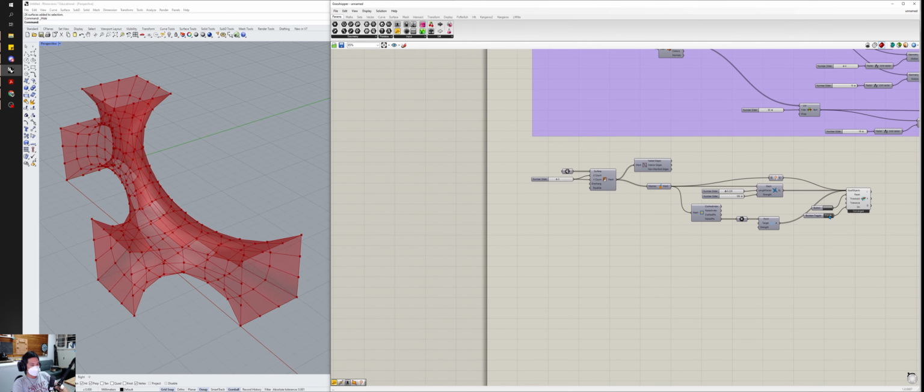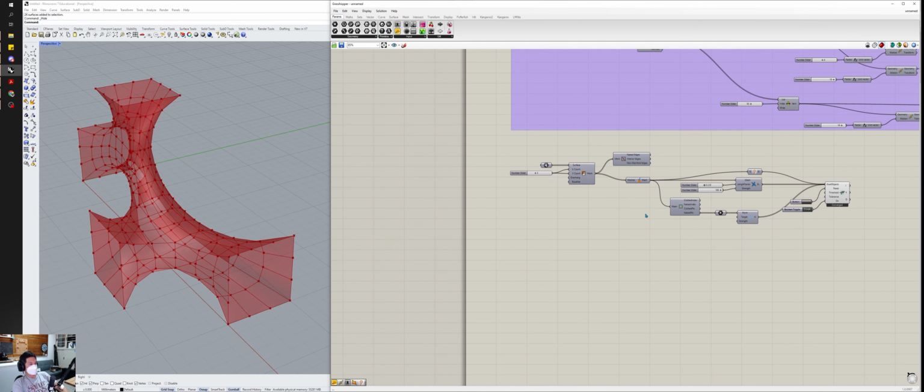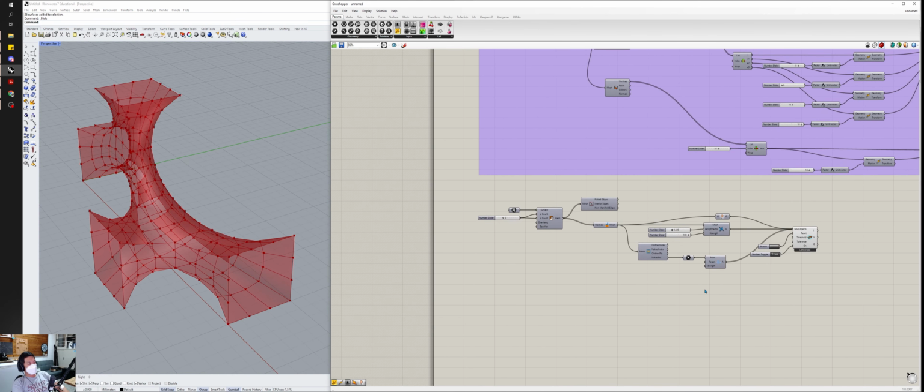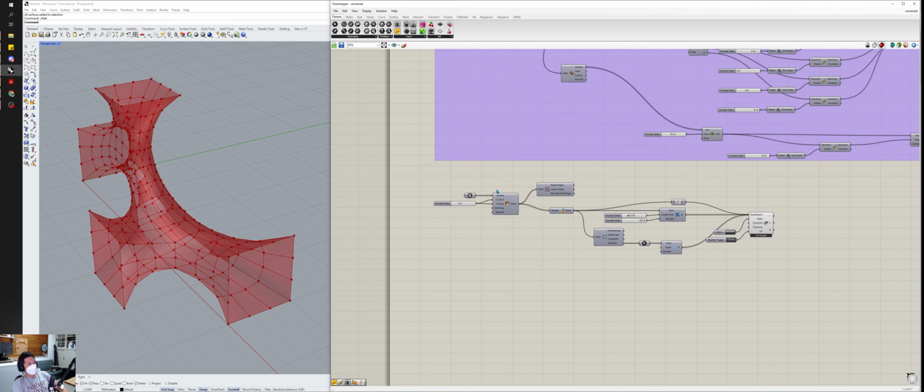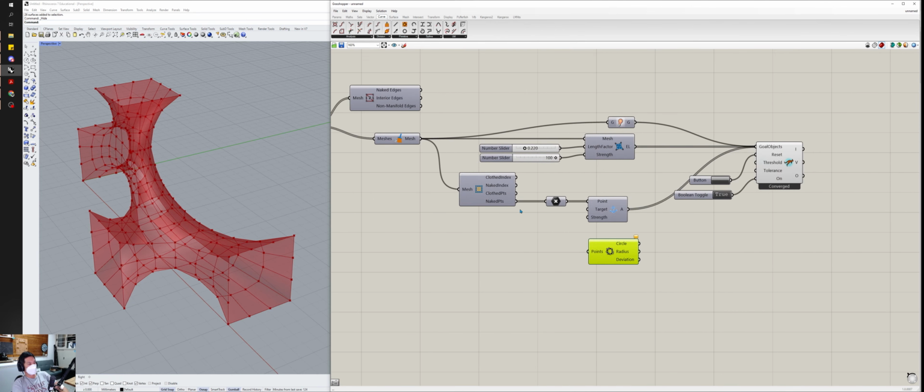To deal with that, what we need to do is bring all those points in to form a circle, right? And the tricky thing about that is, if we were to use a circle component, we go to curve in our primitive and say circle fit, right? I'm going to put those points in, and it's going to generate a circle that fits that set of points.